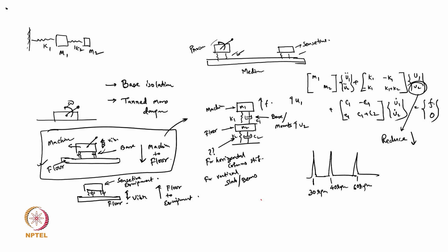Sometimes you may see settings for delicate cloth and so many other things. These all have different types of RPM primarily. And if you are running it in the dryer mode, then the dryer also has particular frequencies. So these are there. So your isolator should be able to reduce the vibration for those frequencies primarily. It must not let the vibration go through at these frequencies.